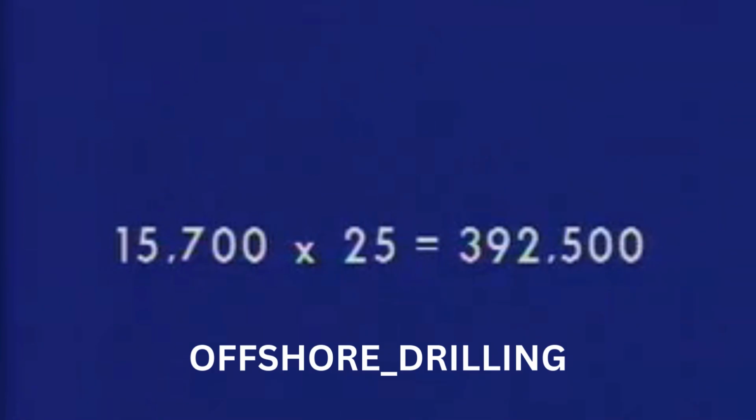The moments for the vessel, as we know, are 392,500 foot-tons, which is figured by multiplying 15,700 tons times 25 feet.